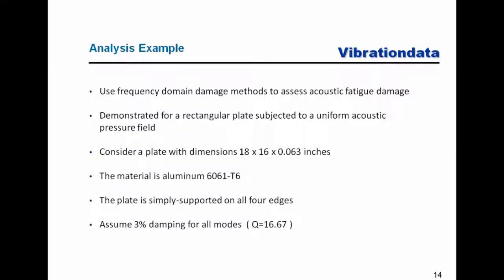Okay, so now we're actually going to get into acoustic fatigue. So we've just covered some basic concepts on acoustic waves and decibel levels, and we found how we could take a sound pressure level. So now we're going to use our frequency domain methods to assess acoustic fatigue damage for a given sound pressure and a given plate or small panel.